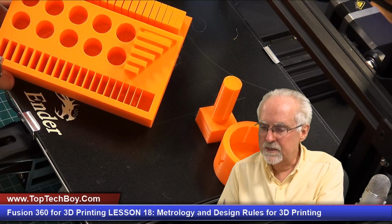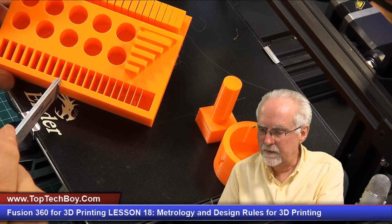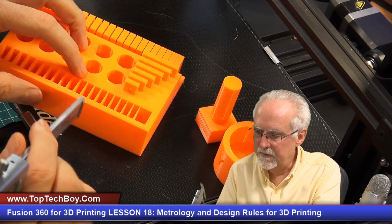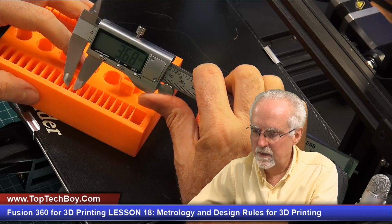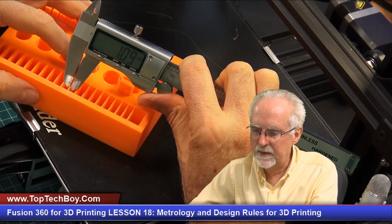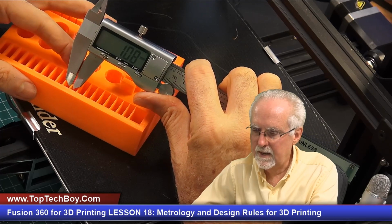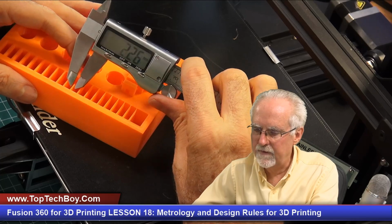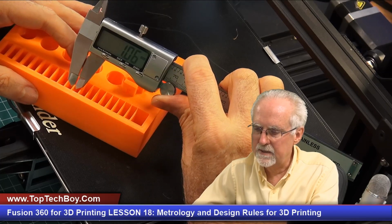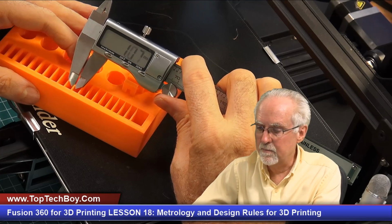Okay, so this is 987654321, and then this would be 1.0. So let's come into this one, and let's see when I tried to print a millimeter line. Okay, I get about 1.05, so that is not terribly surprising. That's back to that kind of 0.05 millimeter precision.